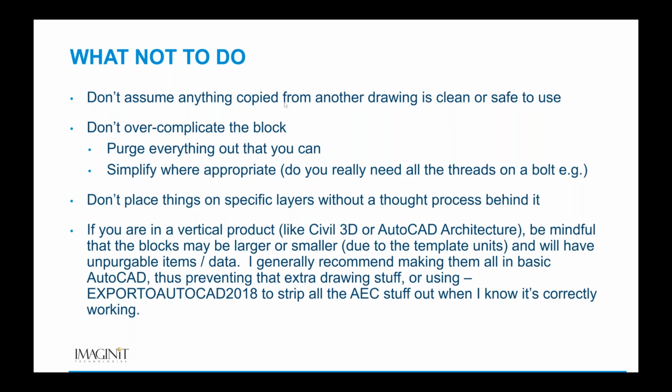Don't place things on specific layers without a thought process behind it. Okay, I'm going to use a door. If you're making a door block and you put it on A-door for architecture, understand that the layer the block is placed on may be different from the layer the block is in. If you accidentally place a door block that has geometry drawn on the A-door layer on layer A-building and you freeze A-building, the block will disappear.